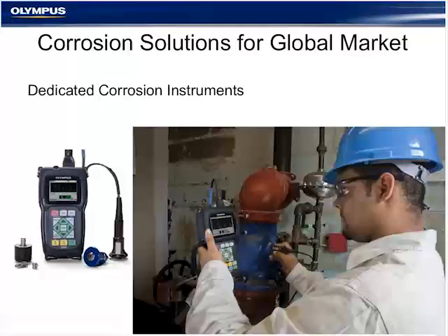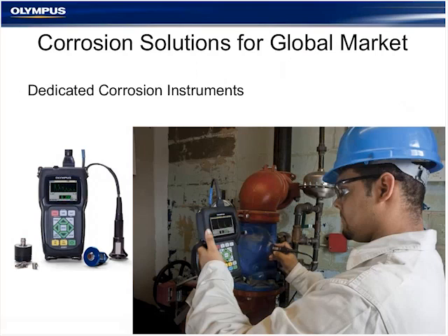So, Coleman had mentioned earlier, if we start looking at these solutions and start from the bottom here, a dedicated corrosion instrument is one of the lower cost single point type instruments that can be used. And this is very much what Coleman is emulating with the flaw detector that he's just done a demonstration on. These products are very accurate at reading corrosion. They are a single point measurement unit, however, and they can be oftentimes very simple to use. The waveform on some of these instruments can be optional, so in some cases you're just looking at the thickness reading and only the thickness reading.